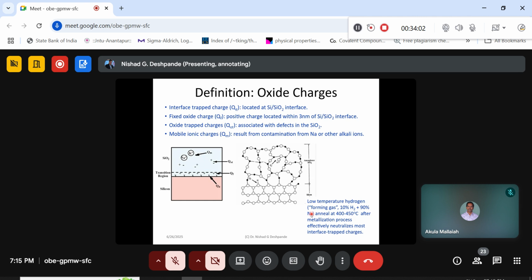Whenever the oxidation is taking place, one can input a proper mixture of gases into the oxidation process. These are inert gases. They are not going to have any kind of interaction within these layers here. Of course, they will just help the oxidation or the diffusion or the reaction process to occur easily.